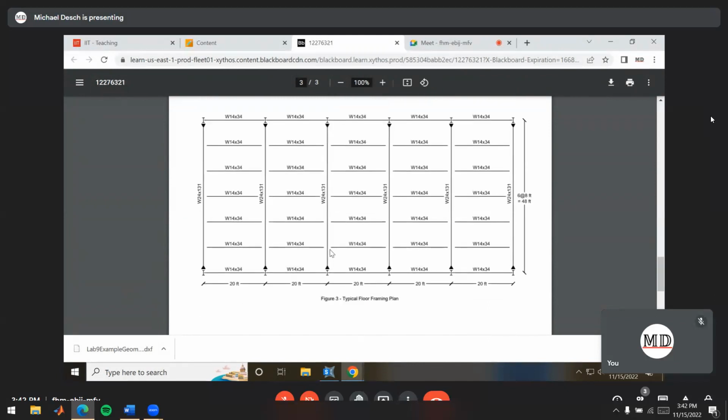And in the plan view here, we don't need moment connections between all of these beams and our girders as well, because having basically simply supported beams between all of the girders here also works. We get a little bit more deflection, but it's generally well within acceptable realms when we're designing here. Does that make sense what we're doing?